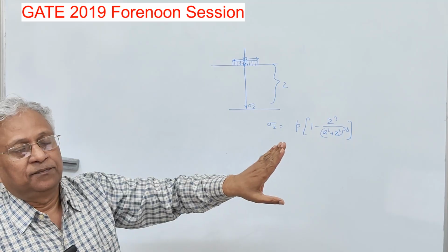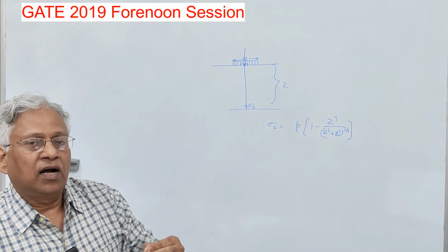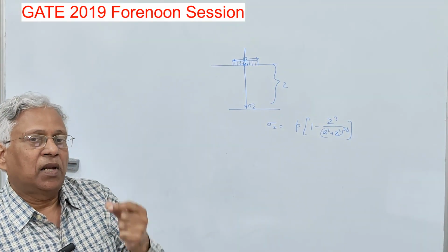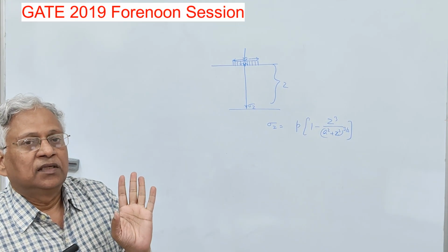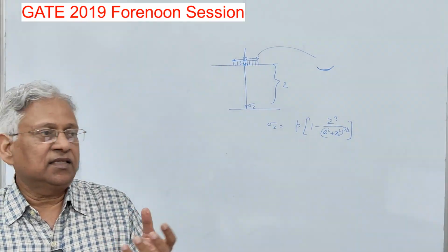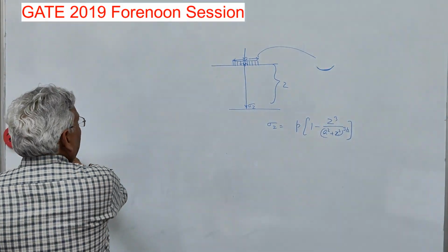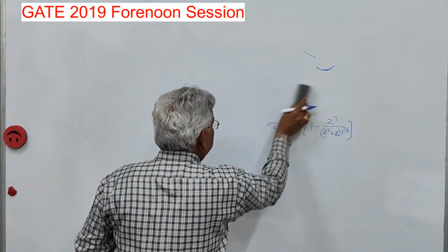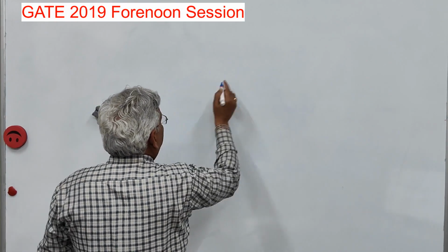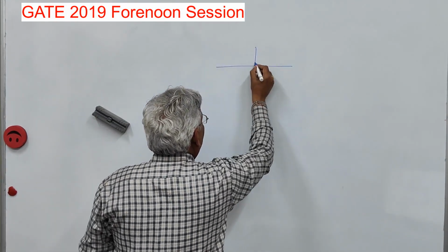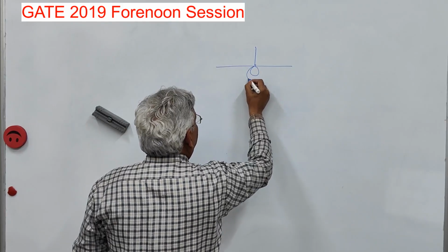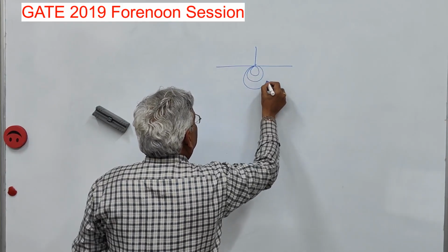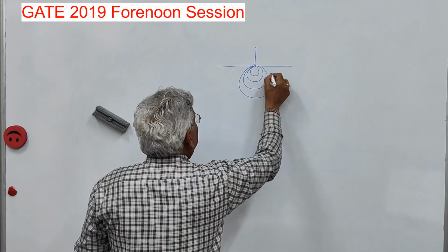to be infinite. And when the stress is very high, then in that case the plastic and elastic flow of material will take place. In that case, the pressure in the soil mass will be in the form of pressure bulb. So this is the load here, concentrated load, and you have the pressure bulb appearing inside the mass.